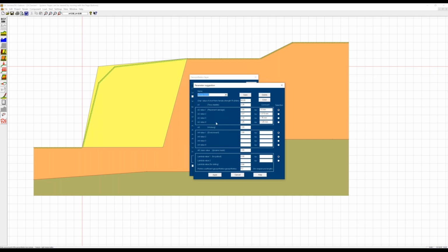And here we have first the strength of the geosynthetics, the characteristic value of the strength, which is reduced by a safety factor and reduced by a number of reduction factors from A1 to A5 for different effects. For example, the time stability of this geosynthetics, the consideration of placement damage, working environment, and dynamic loads. And we have a friction factor, lambda value, for the friction between the geosynthetics and the soil.